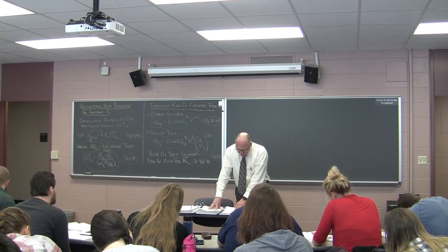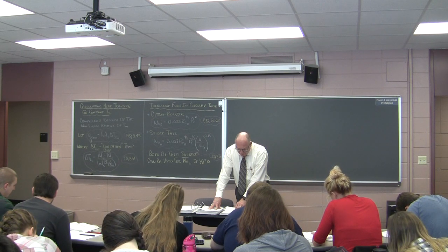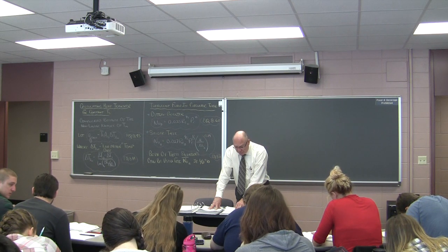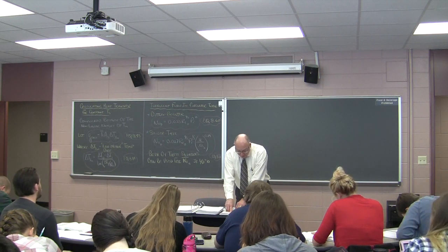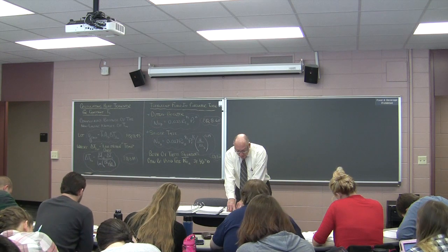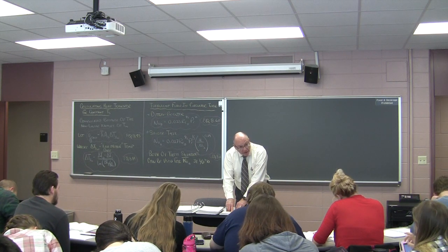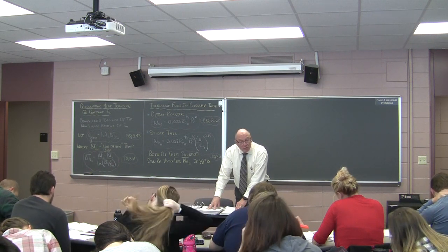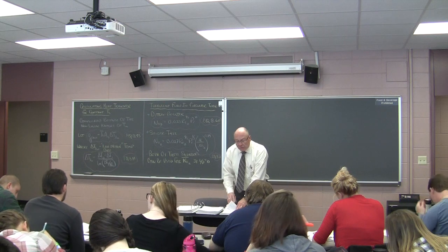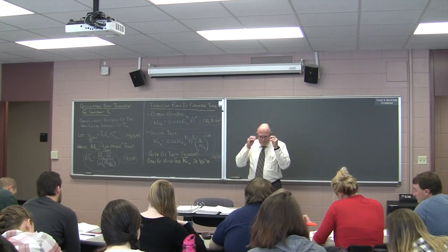The viscosity in the numerator is evaluated at the mean temperature. And by the way, the properties for both the Dittus-Boelter and the Sieder-Tate equation are calculated on the mean temperature, the average mean temperature of the flow, or what you're going to estimate to be the mean temperature of the flow. Now, I'm not going to give you a problem like this in class because it's too confusing.